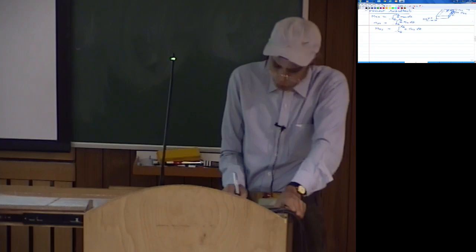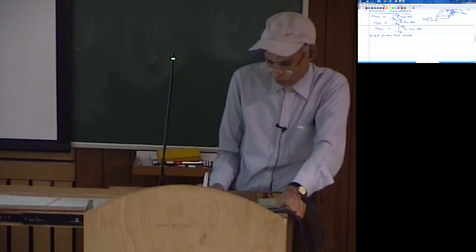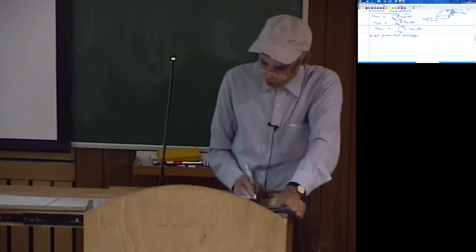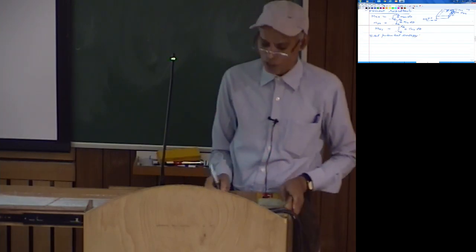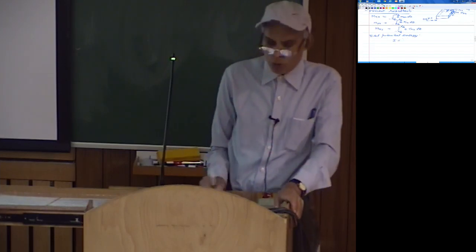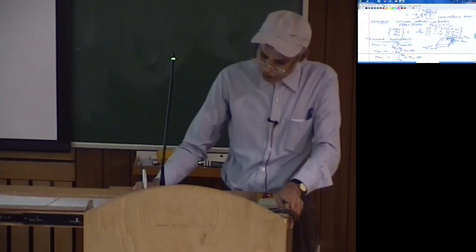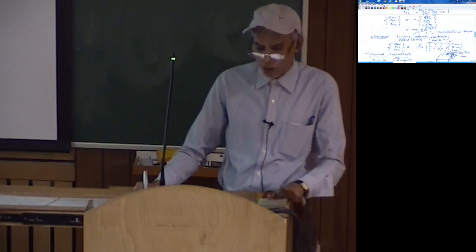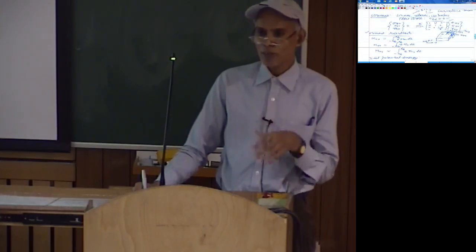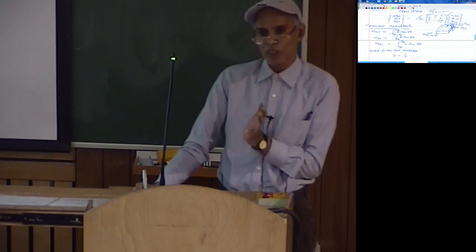Then let me now talk of the next quantity which we will use for the element formulation, the total potential energy, which will consist of strain energy and the potential of external forces. So this will be, as we did earlier, integration over volume, and the volume integral we want to split here into integration with respect to x, y and z. Why that? Because we know the quantities' variation along z direction, so that integration we want to do explicitly and separately.